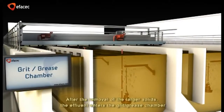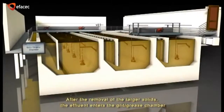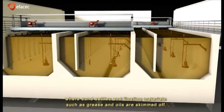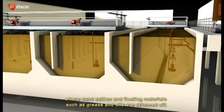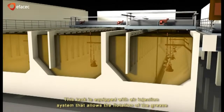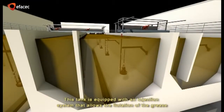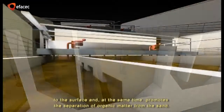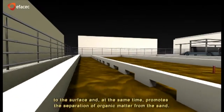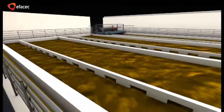After the removal of the larger solids, the effluent enters the grit, or grease chamber, where sand settles, and floating materials such as grease and oils are skimmed off. This tank is equipped with an air injection system that allows the flotation of the grease to the surface and, at the same time, promotes the separation of organic matter from the sand.